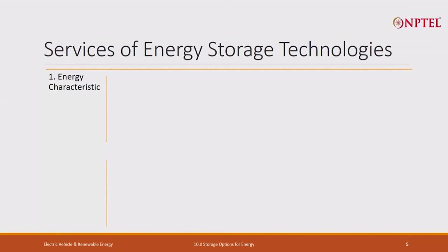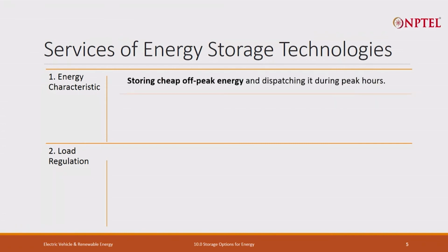What should an energy storage technology do? What are the services? The first one is the energy characteristic. That means storing cheap off-peak energy. When you have a lot of energy and consumption is very low, at that time you store it and dispatch it during peak hours. What does it require? It requires a large storage reservoir for large power capacity, in gigawatt hours.